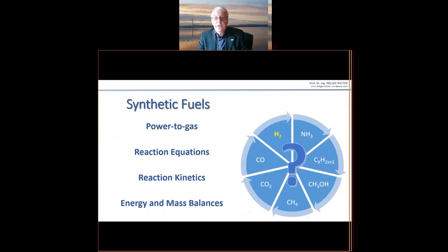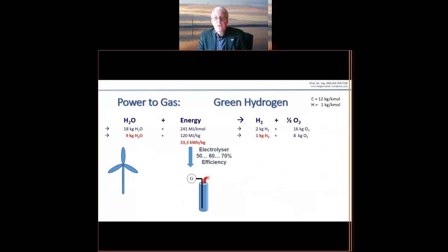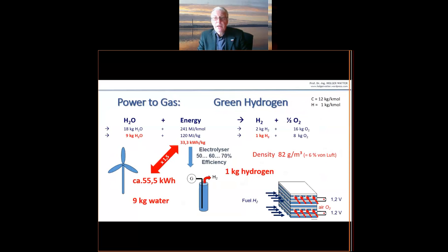In the case of synthetic fuels, the following are presented: power to gas, reaction equations, reaction kinetics, energy and mass balances. Electricity-based synthetic fuels are based on the utilization of wind energy with the help of electrolysis. If you look at the details of the electrolysis, 9 kilograms of treated water are required per kilogram of hydrogen and 55 kilowatt-hours per kilogram of hydrogen.